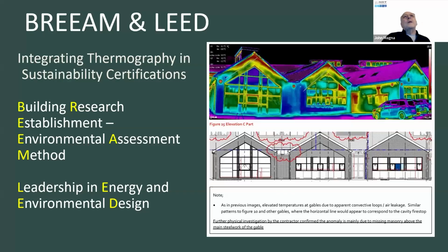We have BREEAM and LEED. The BREEAM and LEED thermographic surveys can count towards commissioning and handover sustainability credit as a means of demonstrating the continuity of insulation and avoidance of thermal bridging and air leakage paths in the building fabric. This type of survey must be conducted by a qualified professional according to a prescribed methodology and standard.